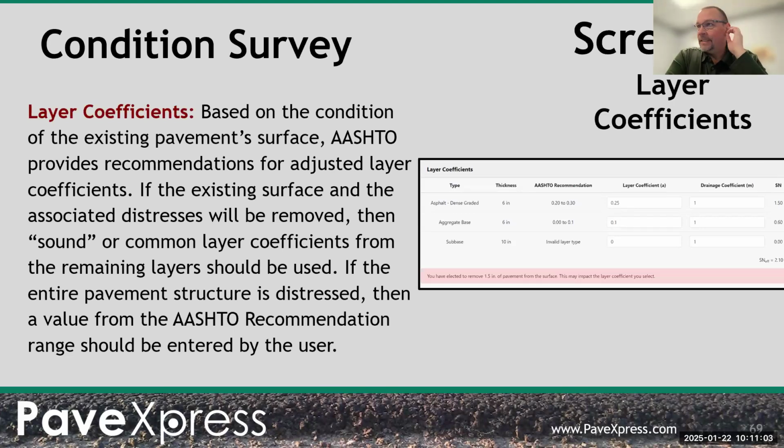I think there are some reference materials in there on how to maybe do that, and there's another program that can estimate that for you. Usually the problem with composite pavements or overlays on concrete pavements is you get so much reflective cracking. It's really hard to characterize that layer below and come up with a thickness design.